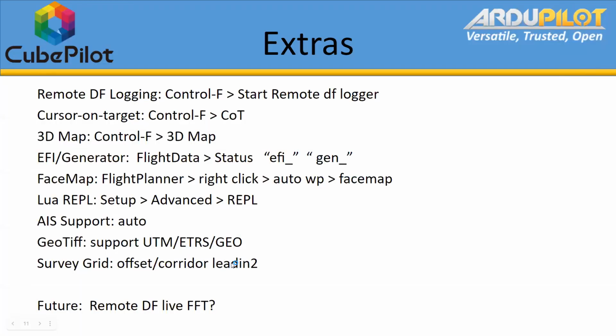Okay, so that's basically it, and the lead-in: there was always a lead-in distance. So this is mainly for plane users. Copter users don't really use lead-in. The ability to specify a lead-in at both ends, basically based on wind factors on the day. So the ability to overfly or fly in or give a bigger lead-in path to actually get online for a plane based on bank angle or wind factors, upwind, downwind legs, etc.